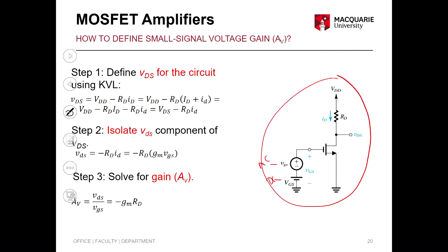But the small signal model applies when you apply small variations to your DC biasing point. If you apply large variations, so for example, someone has a high amplitude voice and talks into this microphone, it goes like crazy. This model won't work. You have to be gently speaking, then the model might work. So just an example. So you can divide this whole circuit into two areas, and then just remove all the DC part. Just analyze the small signal AC part.